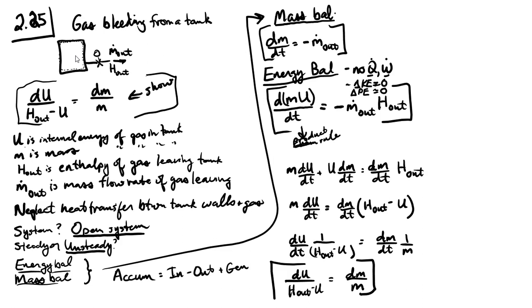We will be plugging in equation of state information, because usually you aren't concerned with the internal energy of what's in the tank. You want to know the temperature, and by using the ideal gas law, if the pressures aren't too high, we can figure out what the temperature profile is as the tank empties.